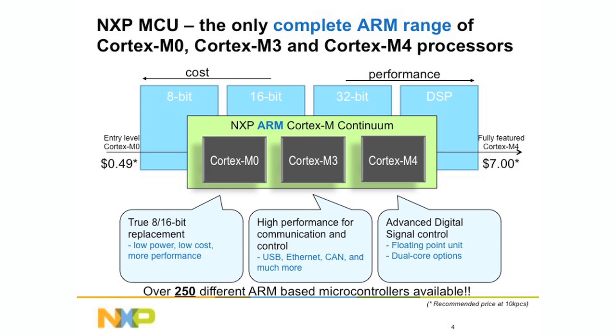I think M4 is where we really bring in a lot of innovation. The dual core implementation was a first from NXP. Also, we brought in a lot more innovation in terms of the peripherals. So we have something called a QSPI, a quad flash interface. As you can imagine, quad SPI flashes are becoming very popular and very cheap, so having a QSPI interface on board would be very beneficial. We also have something called a serial GPIO, SGPIO, which enables you to emulate an I2S, for example, or a UART or an I2C. So it gives the flexibility of adding more peripherals on the fly.